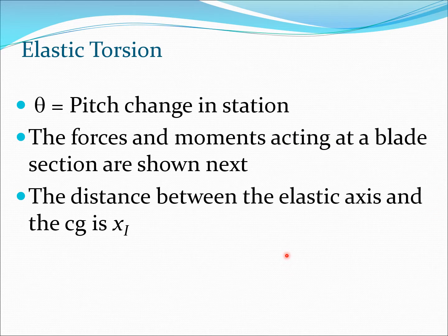So theta is the pitch change in a given station, and now we are going to calculate the forces and moments which act at a blade section. And again, as I mentioned before, the distance between the EA and the CG is x_I, and this is going to play a big role in this particular problem.